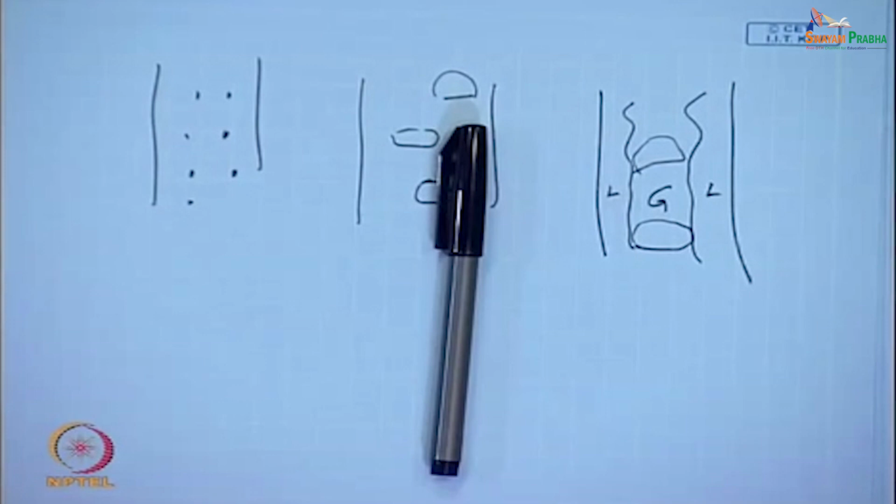Now, let us see under which circumstances we cannot use it at all, even if the two phases are completely mixed with one another. I agree, but maybe it is flowing through an orifice or a very short nozzle. Under that circumstance, what do you expect is going to happen? Completely mixed flow, but flowing through a very short nozzle or an orifice. Orifice means an abrupt contraction. Then what is going to happen? Rapid acceleration will take place.